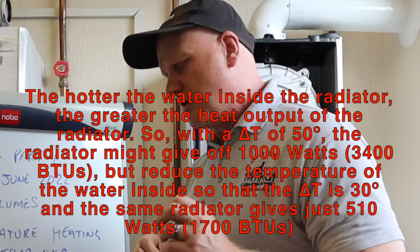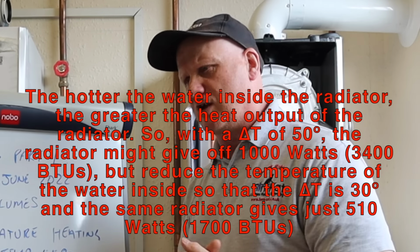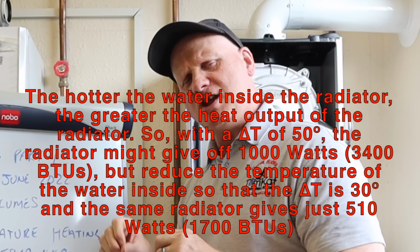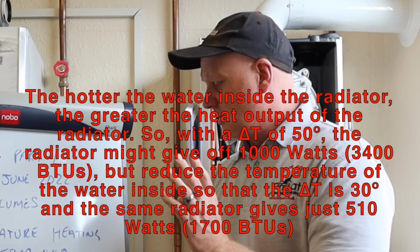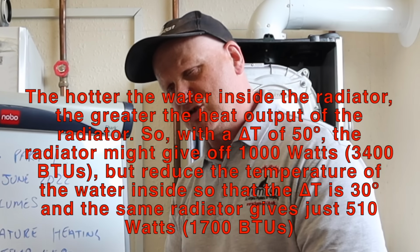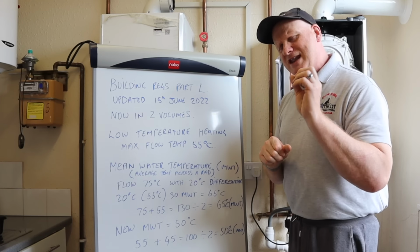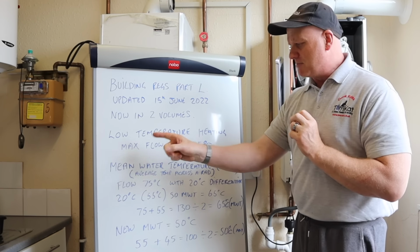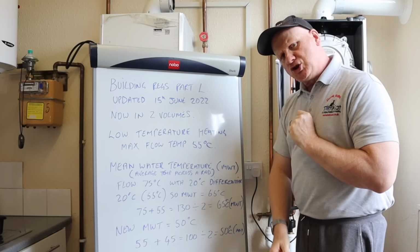So it's important that when you have your boiler serviced and checked, which you should have every year, when your gas engineer comes out to have a look at it, they can explain that more to you and see whether dropping this temperature is viable for you or not. Because what we need to understand is what's called the mean water temperature, or the MWT.